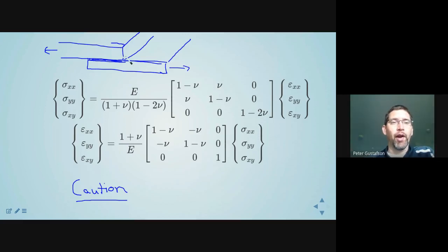Plane stress, a great time to use plane stress is something like that fuselage. And note, it's even interesting that you can use plane strain in a fuselage if you've got an adhesive joint in this cylindrical structure. For the purposes of calculating the adhesive stresses, using the plane strain assumption would be really a great idea. But for calculating the stresses of the parent materials of the fuselage, and neglecting the adhesive, assuming it's doing its job, then plane stress would be more appropriate. So same structure, different aspect of the structure you're looking at, one assumption appropriate for one aspect, another assumption appropriate for another aspect. So you've always got to use your judgment in these circumstances.